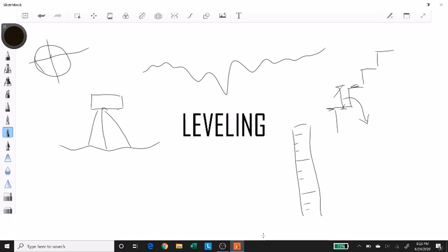When you look through the autolevel instrument, you get a line of sight. This is an imaginary line, which is called your line of sight or line of collimation. When you're looking through this instrument, standing on one side, what you're actually looking at is this crosshair with a telescopic vision, which magnifies it, and at the end of it you place this leveling staff.